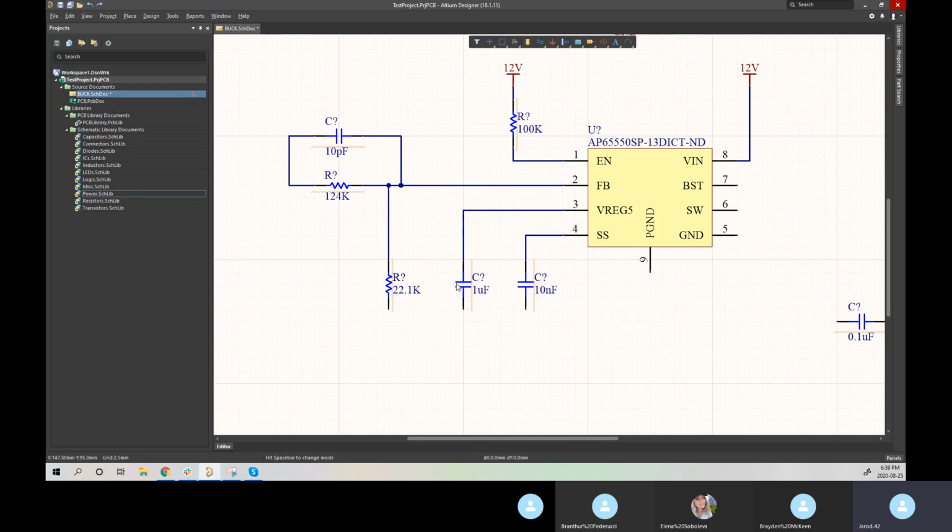If you are running into times where you're having to bring it in close, and it might get a little clustered where your designator is overlapping, you can actually rotate the designators themselves, and you'll sometimes see this by having your designator and comment running up with the component.